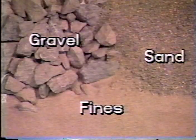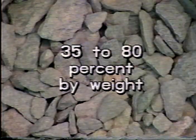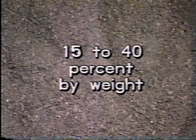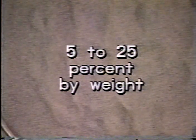The recommended blend of aggregates for an ideal wearing surface are gravel, 35 to 80% by weight, sand, 15 to 40% by weight, fines, 5 to 25% by weight.